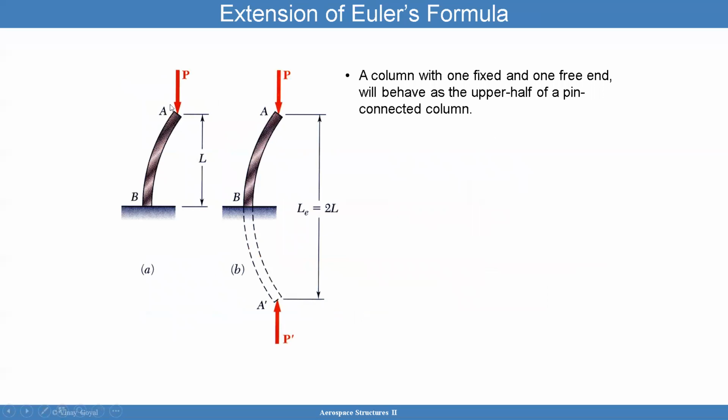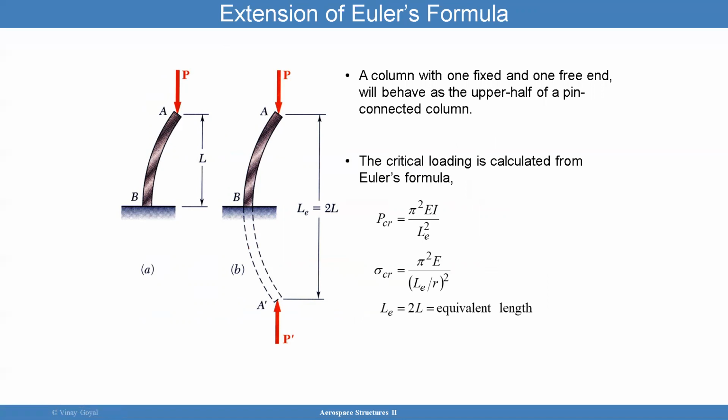You can also have eccentric loading, where the loading is quite eccentric. That can happen in a lot of applications and it needs to be considered. And so a lot of people look at an equivalent length. So say it started a little bit bent. Well, you can come up with an equivalent length and apply a load that will behave just like the buckling formula you saw earlier. And so yeah, any amount of eccentricity can be a problem as well.